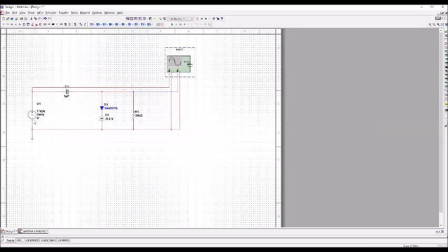So how the circuit works is in the negative half cycle, the diode will be forward biased. So all the current flows through this loop, and the capacitor gets charged to the value of the AC voltage here, peak value, and the voltage V naught output we get is 0, because this is a short circuit, and the current would flow through the short circuit and it would be 0.